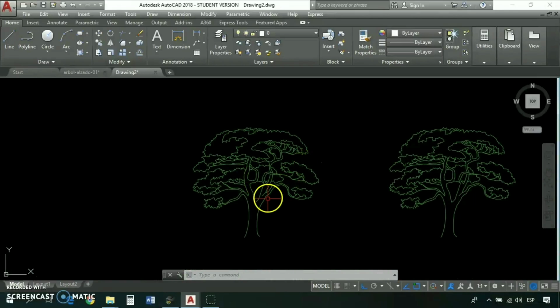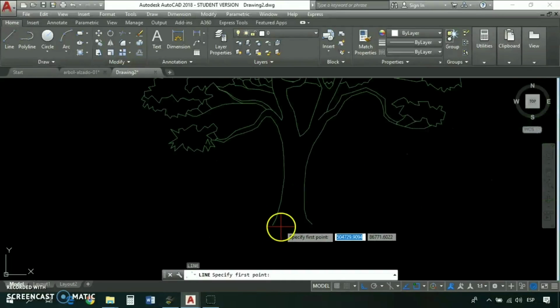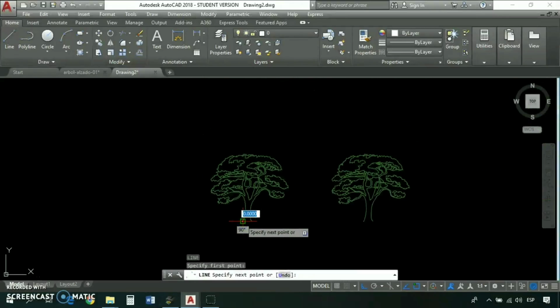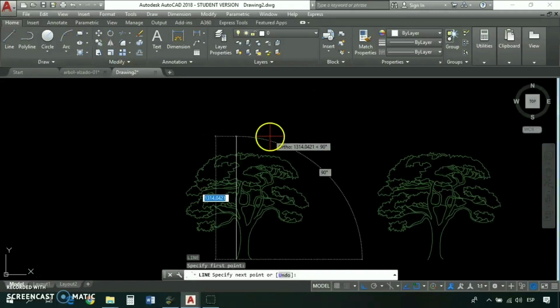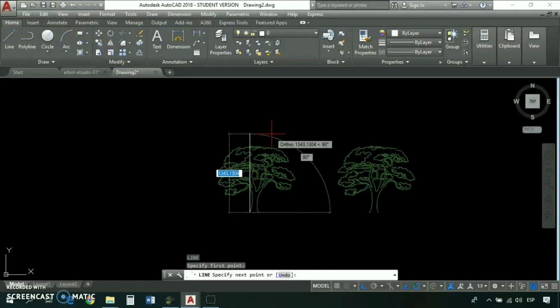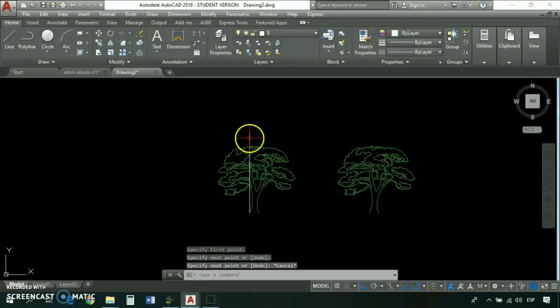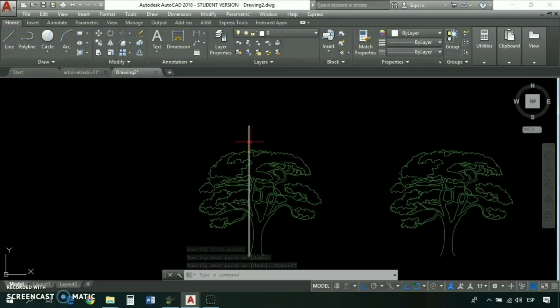Since we already measured it, that is not quite effective, so the other way is to draw a line all over the object. In this case we're going to start bottom to top, and I recommend you use the F8 tool. So you draw a very straight line using the F8 keyboard key, and make sure the line goes across the object. It should be a little bigger than the object. So we have the line where we can reference the height of the object.